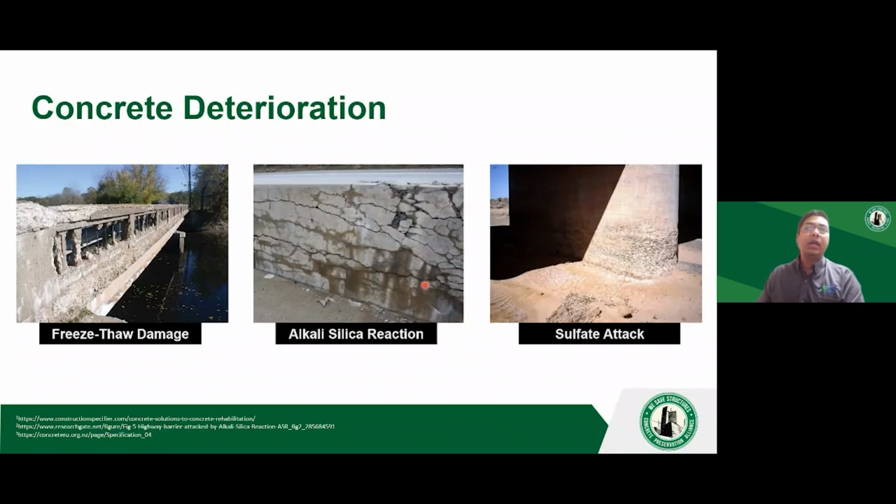So far, we have been attributing most of the concrete issues or deterioration issues to corrosion of steel. Well, that's not necessarily always the case. You can have concrete cracking or spalling because of other issues beyond corrosion. In some cases where your area is experiencing freezing and thawing cycles, the water within your concrete can freeze up, it can expand, and it can crack the concrete. And again, it can be thawed during your warmer temperatures, but during freezing cycles, it again expands and cracks the concrete. This is essentially what you see on the bridge on the left side, where concrete is experiencing freezing and thawing cycles.